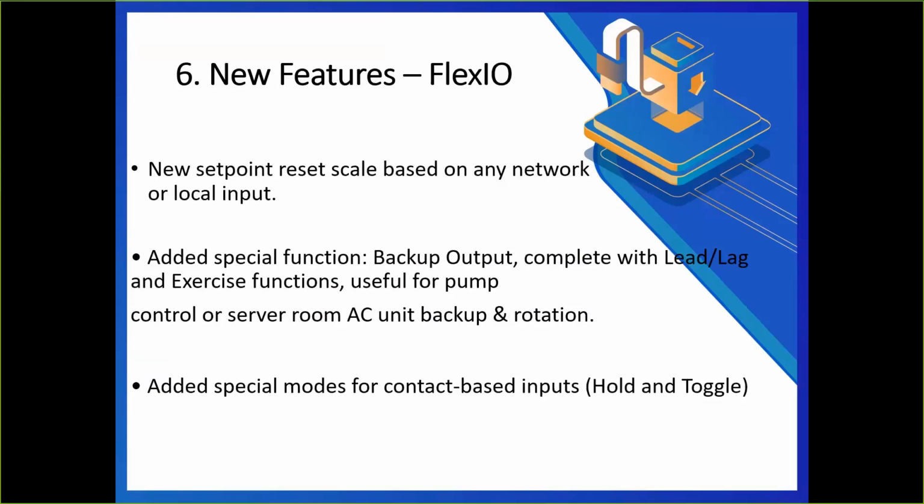Okay, you now get a set point reset. So I can do a linear set point reset. I can do a state-based set point reset, occupied, unoccupied. So I can change my set points based on yet another input rather than having fixed set points.